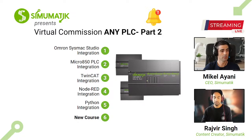In this part, I'm going to show how we can integrate the Simumatik Virtual PLC with a Micro 850 PLC. I have it on my table, powered up, and I'm going to use Connected Components Workbench as the software platform to program it. The mode of communication will be Modbus, which we didn't cover in the last webinar. A lot of PLCs have the Modbus protocol, not only the oldest PLCs from when OPC was not there. So it could be an opportunity for people to use their old PLC or a new one to connect to Simumatik via Modbus and simulate some environment.